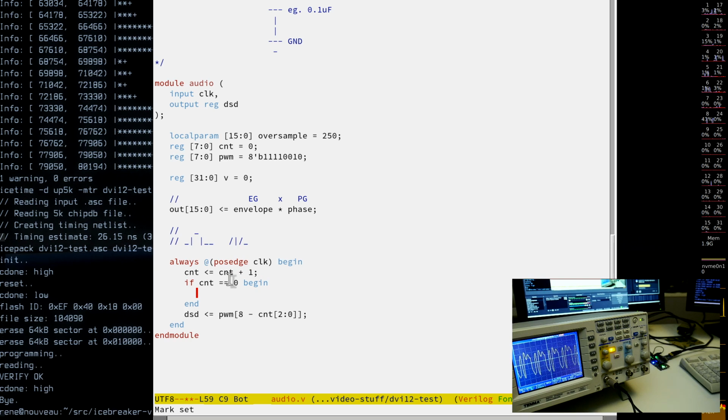Let's synchronize this a little bit so this works. Sample this in the beginning, assign. Maybe we make this 255 for the simple reason that the new computed value for our output PWM would be the next clock. If you are more into Verilog, let me know how to best do this kind of stuff. So, to not lose 1 bit in imprecision and off-by-1 terms, do this here at the end of this count just before the overflow, and increment this. So for example, PWM plus 1.